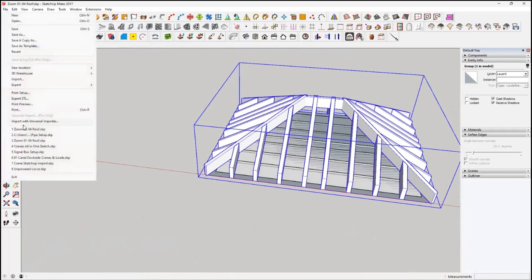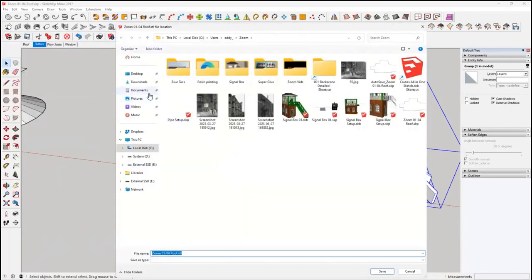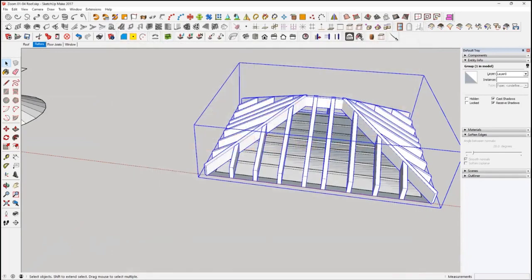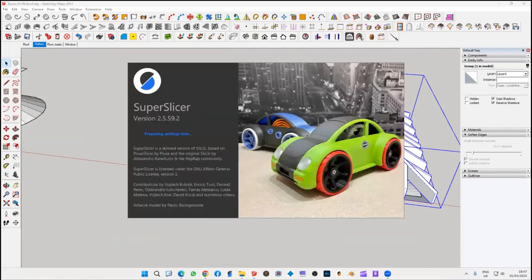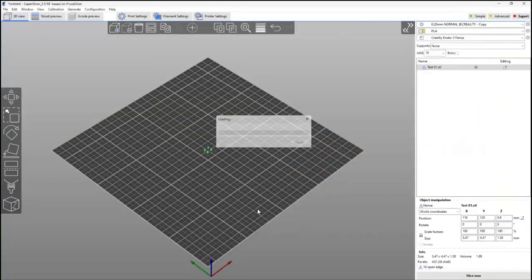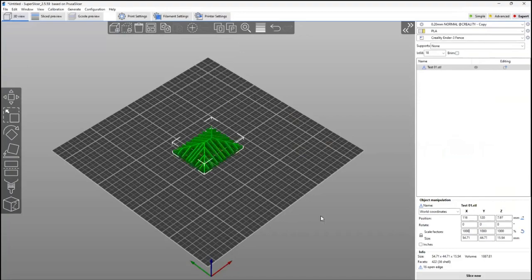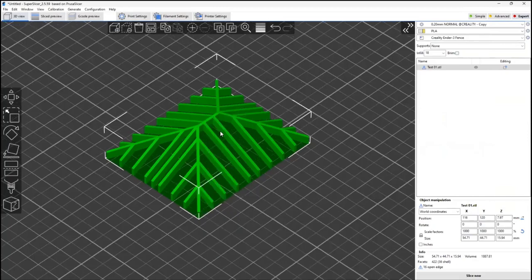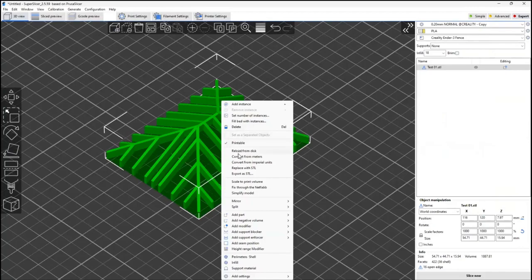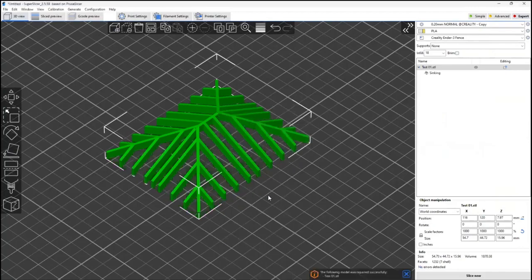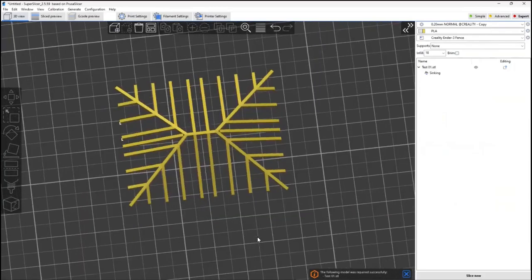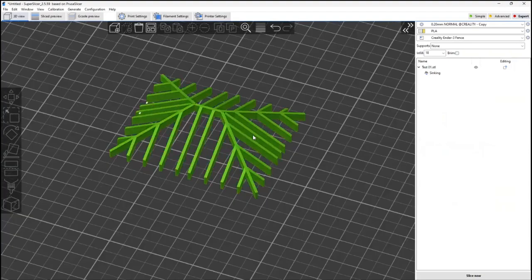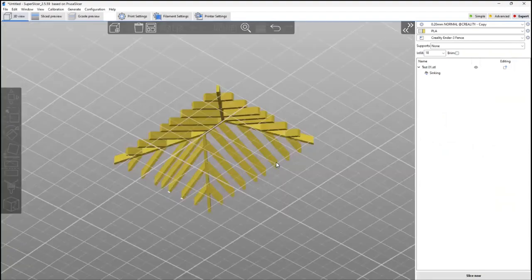On the roof, I exported the STL. What have we got there? Let's have a test. I've got a test there. And if we open up the slicer of choice, well, I think what I didn't delete was the bottom bit there. So if we right click and fix through Netfabb, yeah, there we go. That gives you rafters, and that won't FDM print, but you could slice it to FDM print it, but that will resin print.